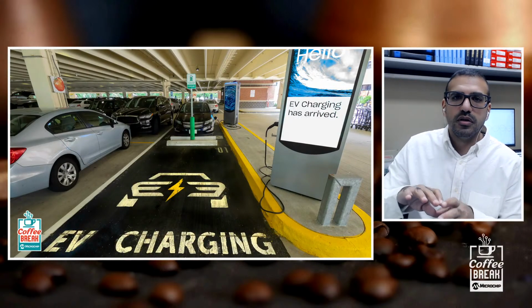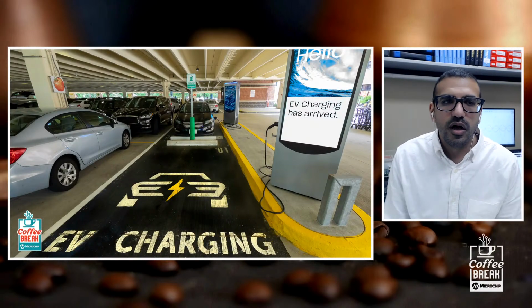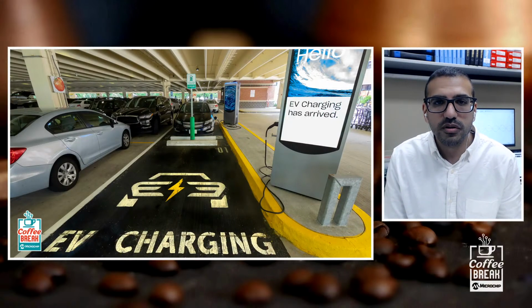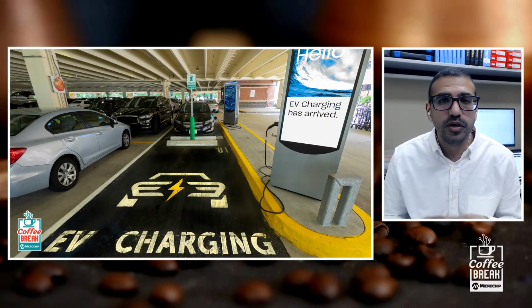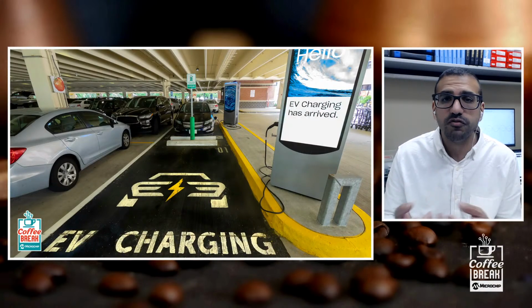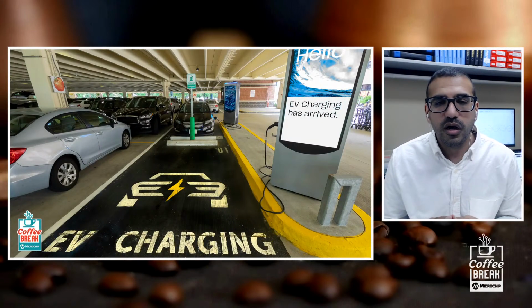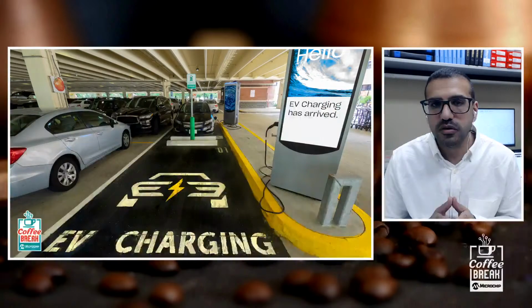And then you look downstream to the vehicle itself. How does the charging station talk to the vehicle? There's different protocols for that. There's a well-known standard called CHAdeMO, and that uses a CAN interface. And then there's the more popular now CCS, which will use PLC, power line communications, using the HomePlug Green PHY interface, where there's communication over the pilot wire to the vehicle. So you have that handshaking and communication, and that's how you establish a reliable communication with the vehicle.